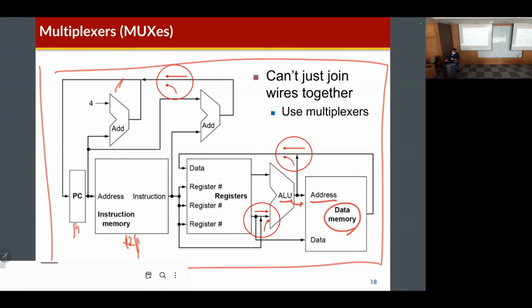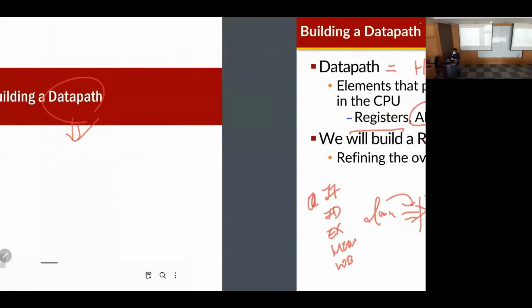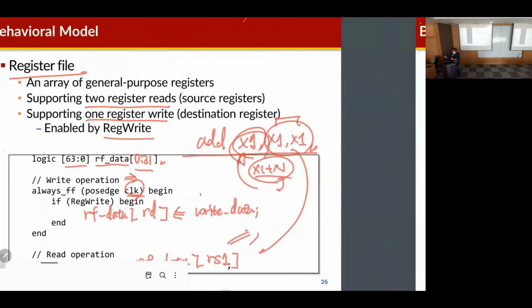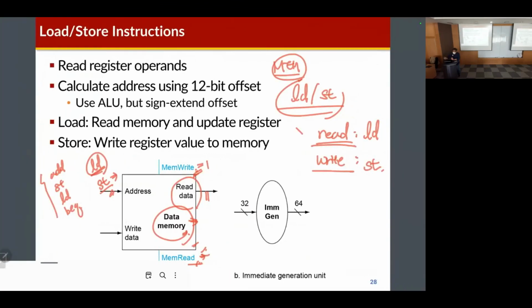So whenever the ALU generates an output, the address value changes, the address is given to the data memory, and the data memory needs to work for the new data out. So it's kind of a waste of power. But this is not harmful for the result of this single cycle processor.